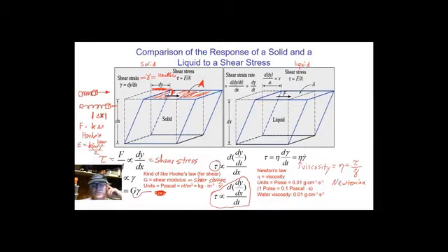The opposite of elastic is viscous. The opposite of storage is loss. Okay? So there's actually a thing called the loss modulus that goes with the viscosity. It's not the viscosity, but it goes with the viscosity. So you have storage of energy, you have loss of energy. In any substance you care to name is a little bit of both. Everything is viscoelastic.